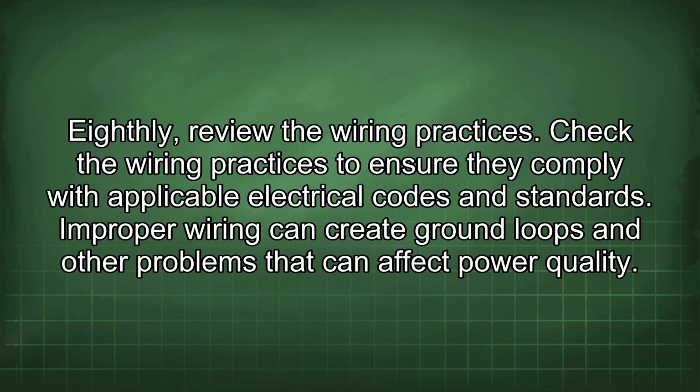Eighthly, review the wiring practices. Check the wiring practices to ensure they comply with applicable electrical codes and standards. Improper wiring can create ground loops and other problems that could affect power quality.